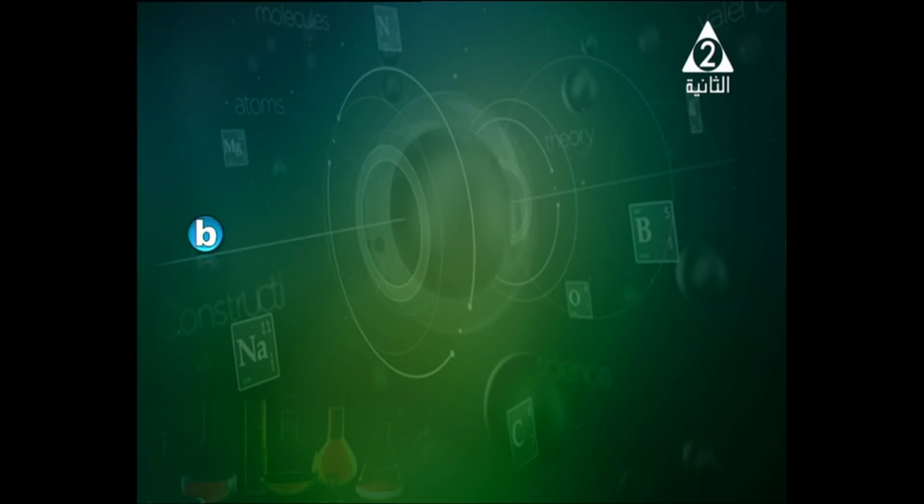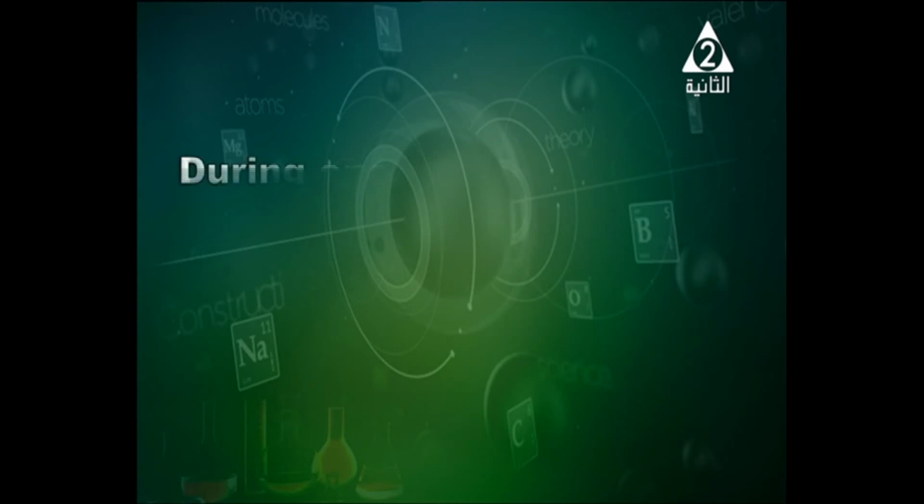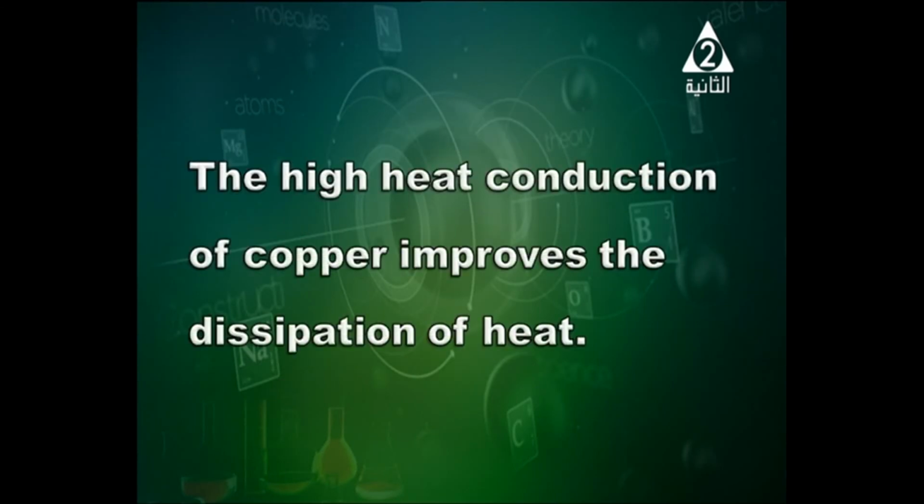What about the use of the copper block in the tube? Okay. During operation of the device, the temperature of the tungsten target highly rises. The high heat conduction of copper improves the dissipation of heat. So we need to get rid of the heat produced. So we use copper because it is simply a good conductor of heat. So it dissipates the produced heat to the surroundings.